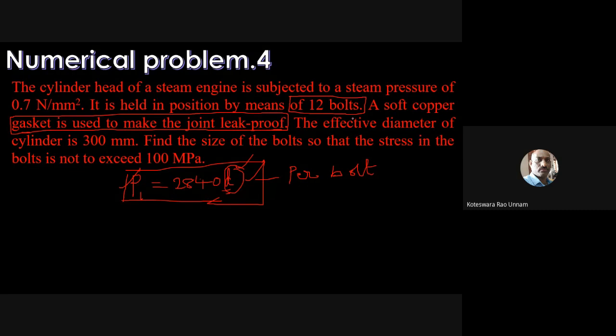Then the external load is taken by the 12 bolts here. In the same cylinder head, he has used 12 bolts to make the connection. So whatever load comes on the cylinder head because of the internal pressure, that load is taken by these 12 bolts. So here also you need to calculate for each bolt how much load is there. So that is the external load.